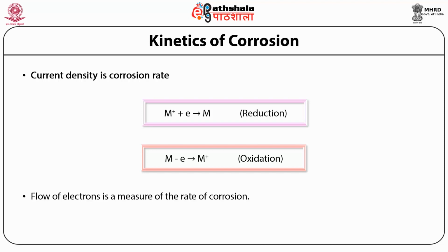The amount of dissolution of a metal can be found from the following formula: W = I × t × A / (n × F), where W is the mass loss, and I, t, A, n and F are the current in amperes, time duration of the exposure, atomic weight of the dissolving metal, number of electrons, and Faraday's constant respectively.